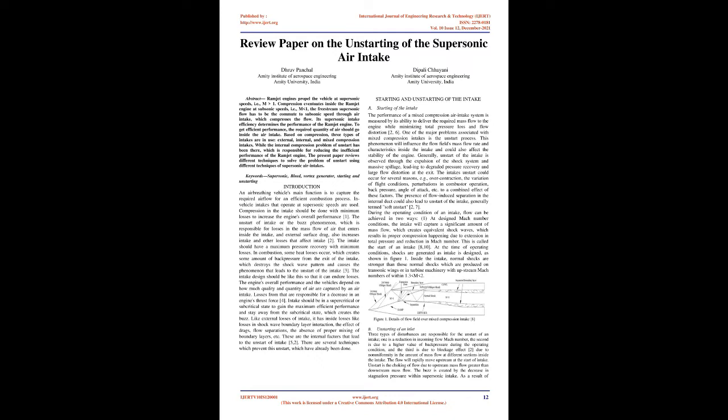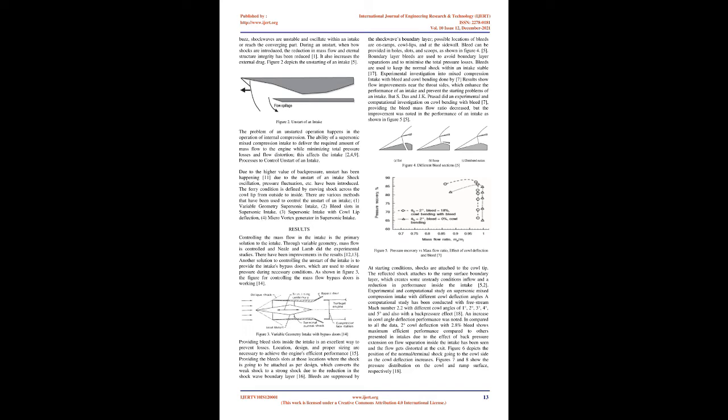Starting and unstarting of the intake. A. Starting of the intake. The performance of a mixed compression air intake system is measured by its ability to deliver the required mass flow to the engine while minimizing total pressure loss and flow distortion. One of the major problems associated with mixed compression intakes is the unstart process.